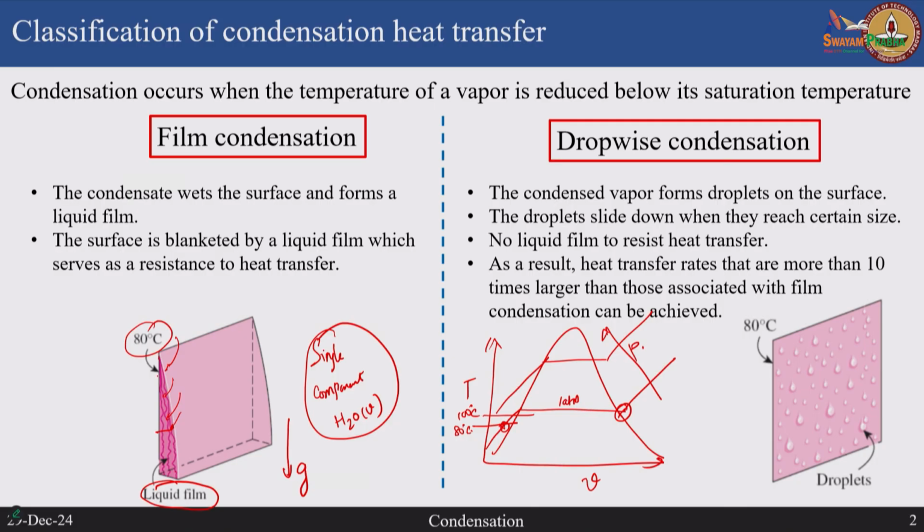Now, the other type of condensation is nucleate condensation, where droplets nucleate, just like bubbles nucleate in boiling. The droplets grow in size as the condensation progresses, and depending on the type of surface, these droplets can coalesce with smaller drops and become larger drops, and finally, once one reaches a critical size, if you keep the surface tilted or vertical, due to gravity it has to roll down.